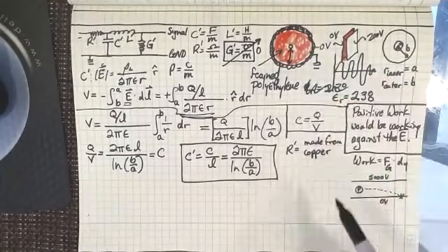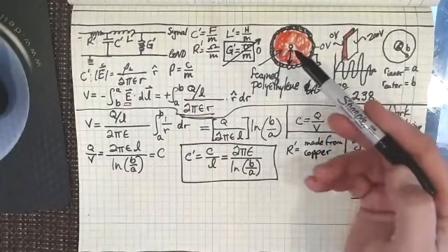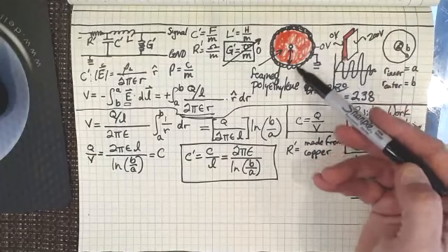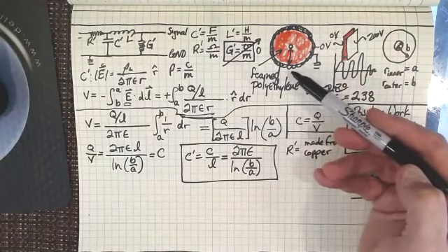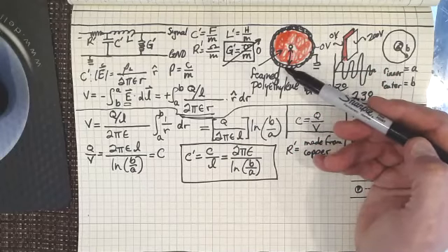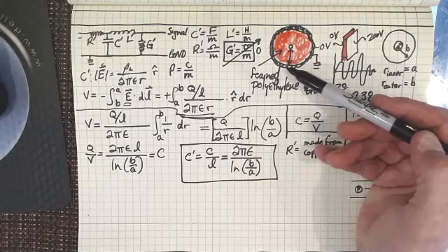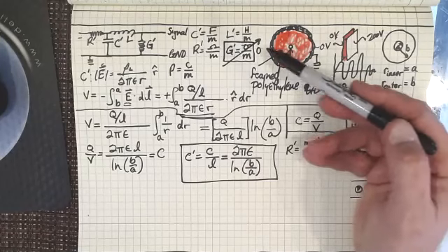That's because we've got a lot more surface area out there. We don't need as good of a conductor on the outside. Copper is about twice as good a conductor as aluminum. And this isn't pure electrical aluminum out here. This is tensile aluminum, which is still highly conductive and great for a ground shield.